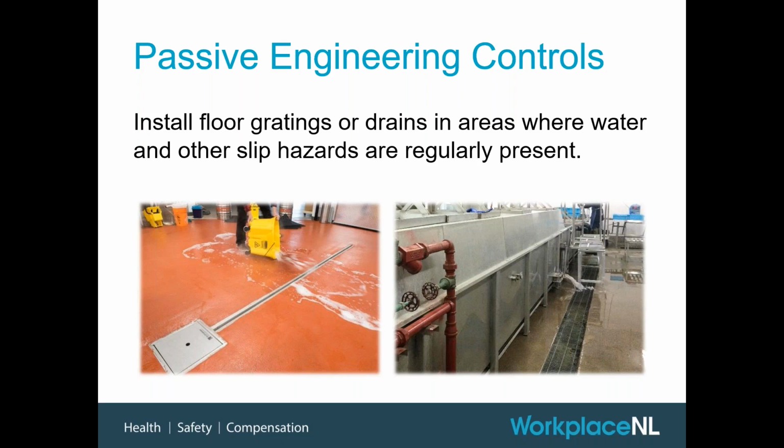I've seen some employers actually building their floors such that they angle down towards central drains, similar to things we try to do with our highways, and even if you're installing tile in a bathroom, there's little things you can do there. I am a big fan of the floor grading as well in porches, and I'm just going to call it the porch.